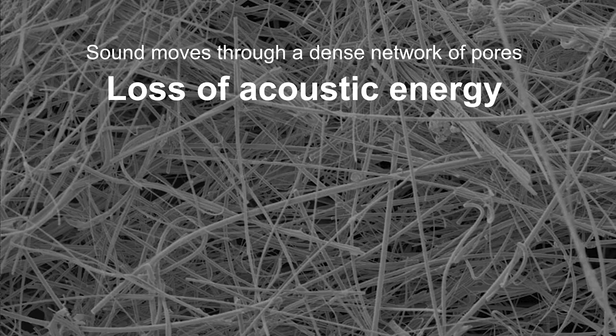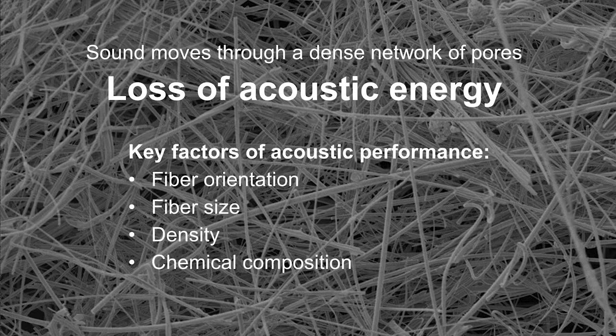So while the sound is doing its best to move through this dense network of pores, a certain physical phenomenon happens. We call this physical phenomenon the loss of acoustic energy. And this loss of acoustic energy is governed by many parameters. But we can say that the most important ones are the fiber orientation, fiber size, the density of the entire insulation package, and of course the chemical composition. So something that we agreed didn't look so spectacular at the first glance is actually a very sophisticated product with a lot of room for the optimization of its performance.